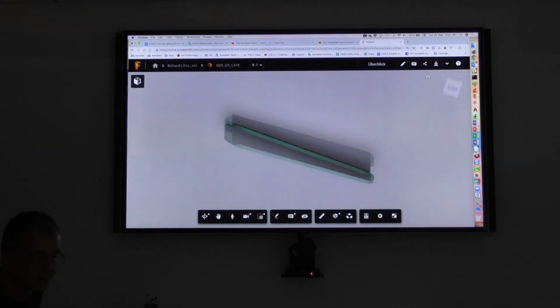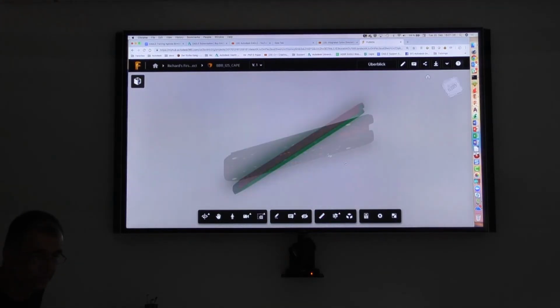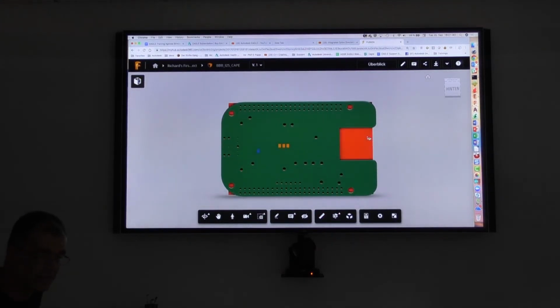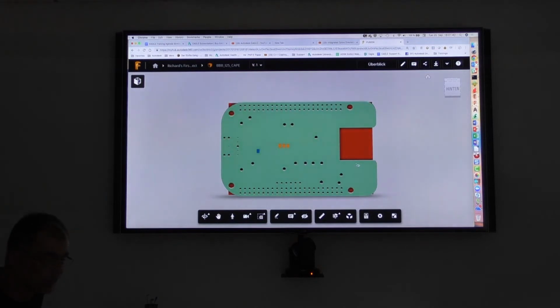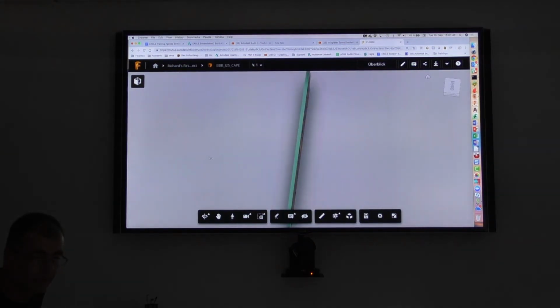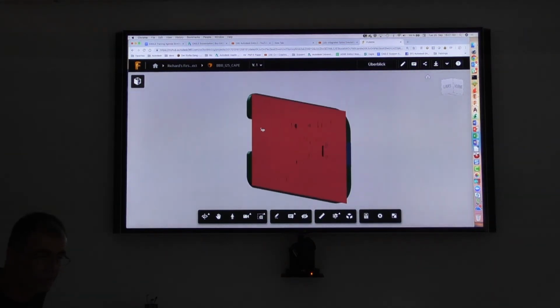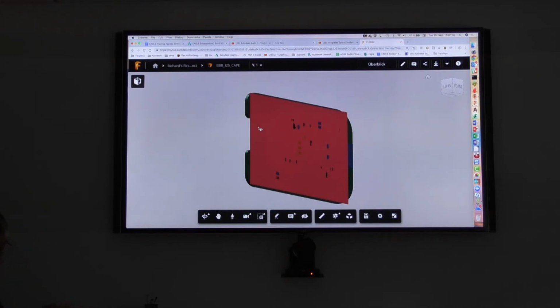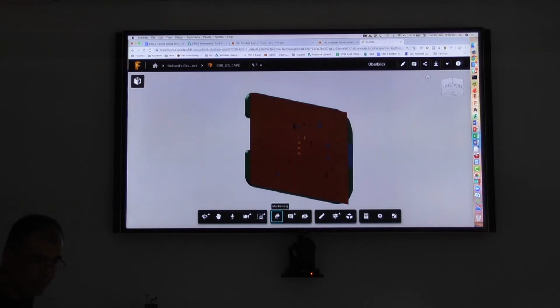I see that the copper plane is not very well represented. That's something they're working on because it should of course not be there. It should be cut out as well. This is the place where we usually would say, okay, that's my step model. I could share it with other team colleagues here. This preview, they could look into it. You could do some markup, add some comments or whatever.